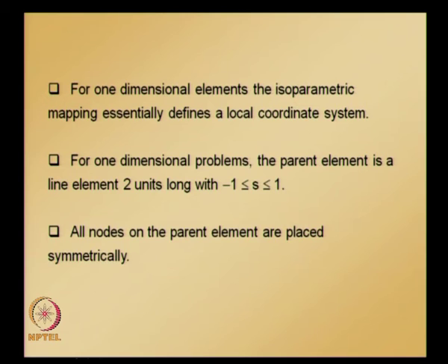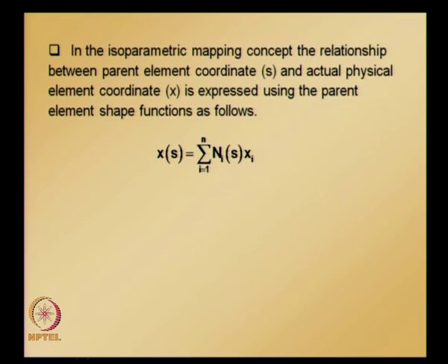In the isoparametric mapping concept, the relationship between the parent element coordinate s and actual element coordinate x is expressed using parent element shape functions as follows.